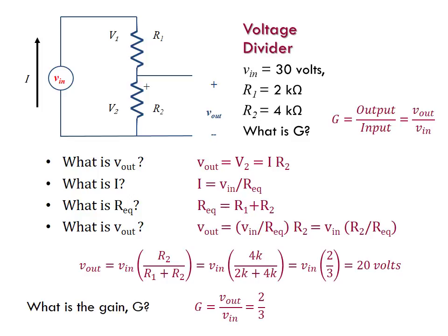So in this specific case, if we plug through these values, again, you should do this so you have more familiarity with them. You're going to see our gain is 2/3, which means whatever our V in is at these particular resistor values, our V out is going to be 2/3 of our V in. Again, 2/3, you can turn that into a percentage as well, however you want to do this, to be able to understand that you have essentially a gain there. It's a gain of less than 1 because you're taking power out of the system with that first resistor, which makes sense conceptually. But this is a neat way of looking at voltage dividers.